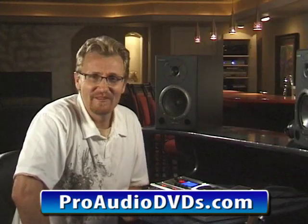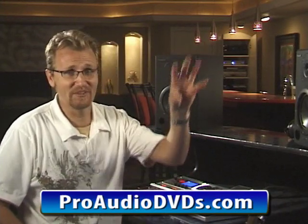Please take care with this approach, as it will overwrite anything that is currently in those locations within your GT-10. So using the librarian requires a little bit of thought as to where the information is going. I would always recommend making a complete backup before you get started, and call it safety with today's data. Burn it onto a CDR, put it up on the shelf. Of course, you can always restore the GT-10 to its factory condition underneath system, a factory reset. We'll look at that in a moment. But if you've spent a bunch of time making your own user patches, boy, it's really easy to wipe them out with a librarian if you're not paying attention.